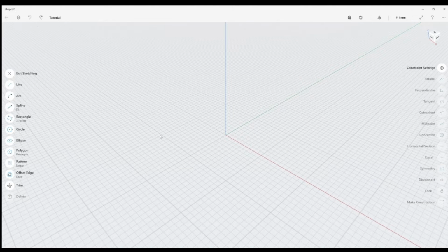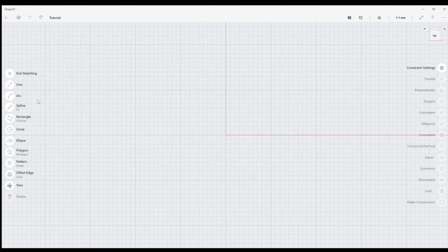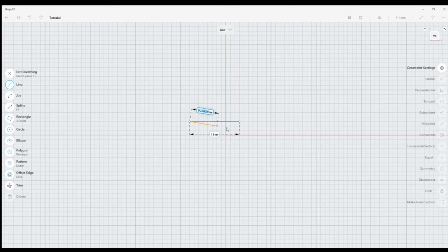So if I'm doing a line, and we'll go to a top view, and I'll get in and show you how I just did that. But let's say I want a line. If you notice, when I click, it puts it right there at the intersection of two grid lines. And if I come over here and I click again, you'll notice it automatically snapped right into another grid line, the junction of those two grids. That's what snap settings in a nutshell does.